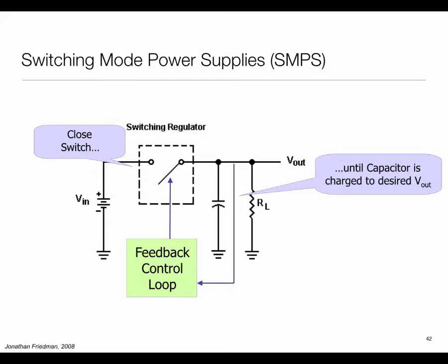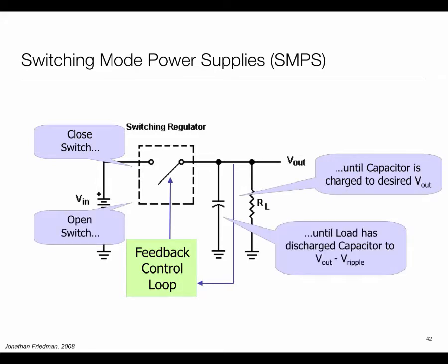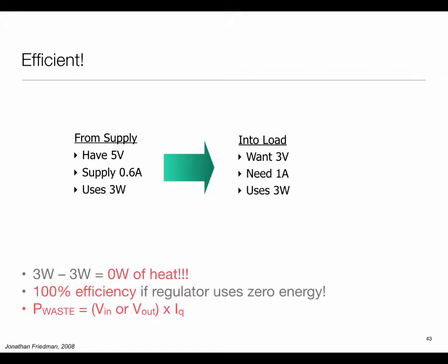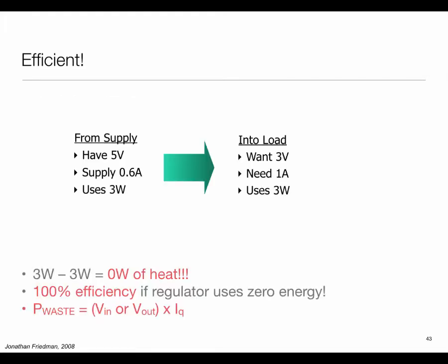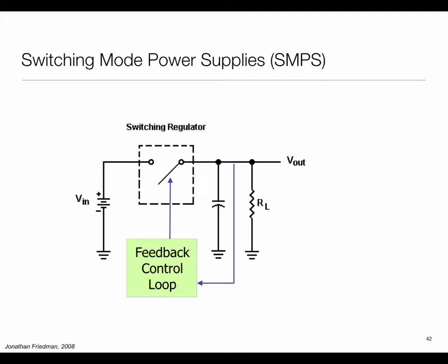We basically have a little animation to walk through it. We alternate between open and closed. The main point is they're extremely efficient. You can get close to 100%, or in the 90s, in efficiency. But there are disadvantages also. If you ever monitor the voltage on the power line of your home, or while your laptop is plugged in, these things are switching mode power supplies, and when we rapidly turn this guy on and off, usually at tens of kilohertz, it injects a lot of noise out there, and that can affect the performance of more sensitive circuits.